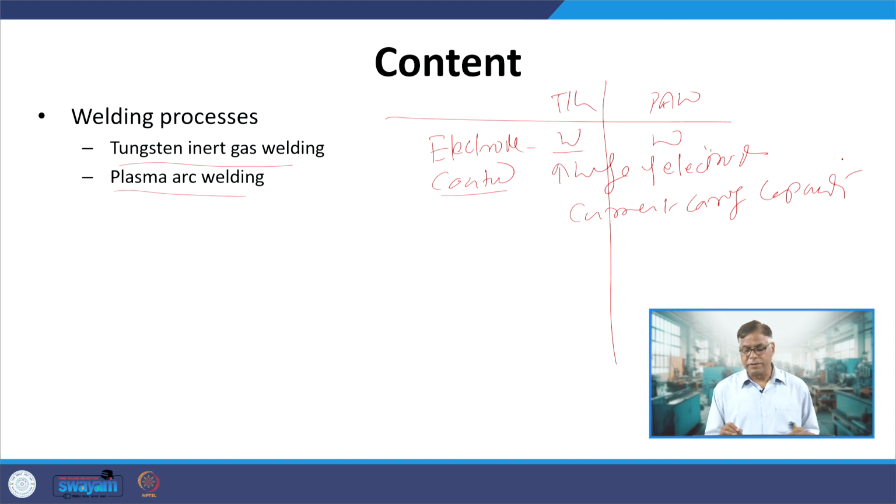For example, for a given diameter of tungsten electrode, if the current carrying capacity is 120 ampere, by coating the electrode it can be increased to 150 or 160 for the same life, because if the coating is not done, thermal degradation is fast. This type of electrode is used with both processes.